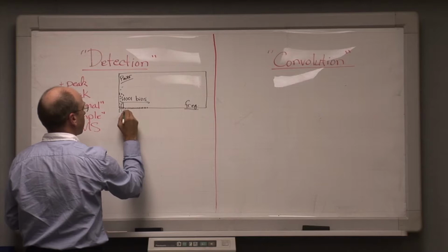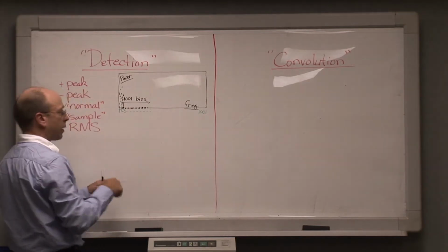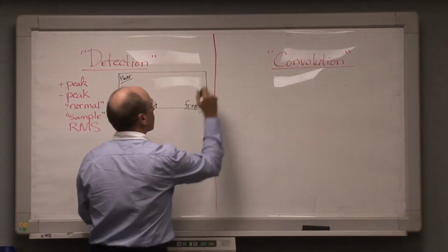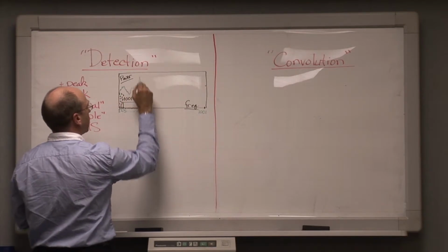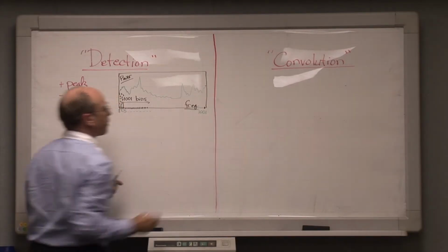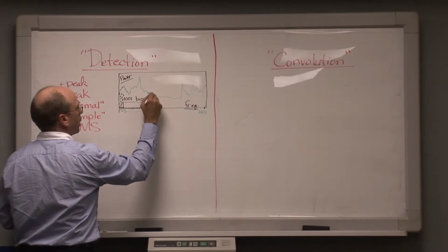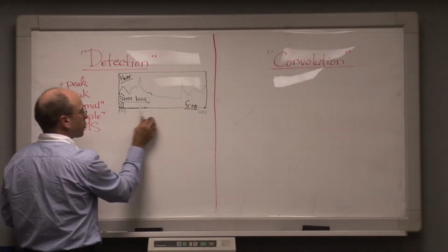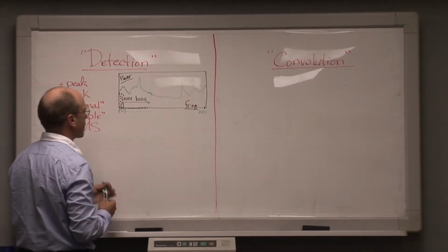Here's the power level for bin number 3, and so forth across until we finally get to the displayed power level in bin number 1001, at the far right-hand side of the screen. To the eye, these look like they're fairly well connected, but bear in mind that these are typically discrete points that are in fact being displayed as a set of bins, and that the spectrum analyzer's frequency sweeping here is synchronized with the sweeping of that voltage-controlled oscillator that we see down at the IF stage.